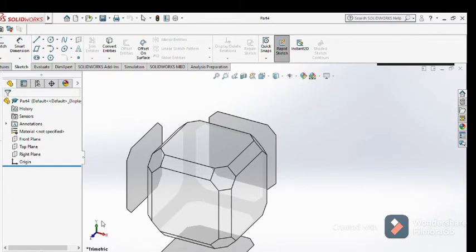Like I said in my last video, I was doing an isometric, and you need to know your orthographic projections. This is the first angle orthographic projection. The first figure, the one that looks like a half moon, is the front view, the one below it is the top view, and then the left view. We're going to use most of the measurements on the top view and front view. The left view is just for touch-ups to add in some other features.